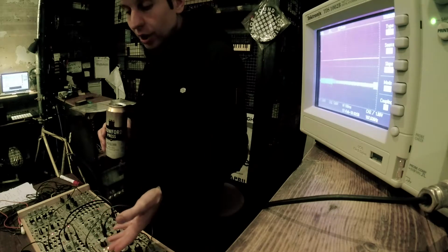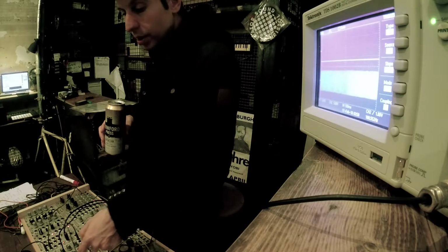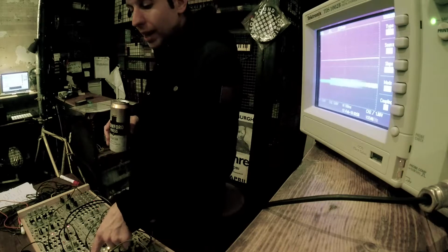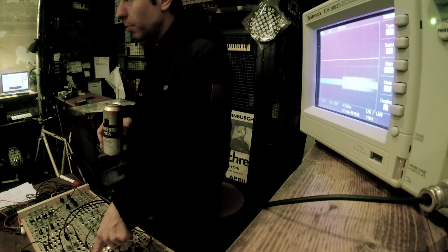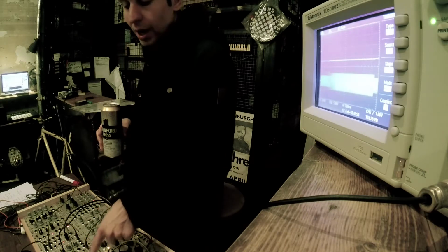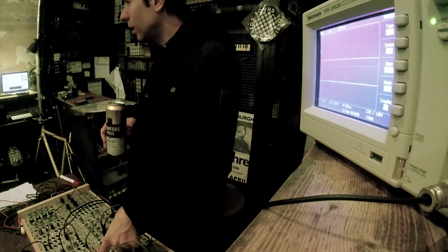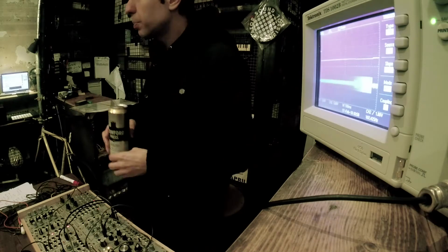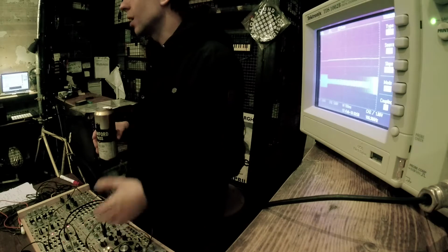You've heard here that I managed to run it up to 16K. What you also heard is that I got this subharmonic series coming up when I increased the triggering frequency, and earlier today I figured it was about 3K, the top limit in terms of steps. I can get 3,000 steps per second and not more.